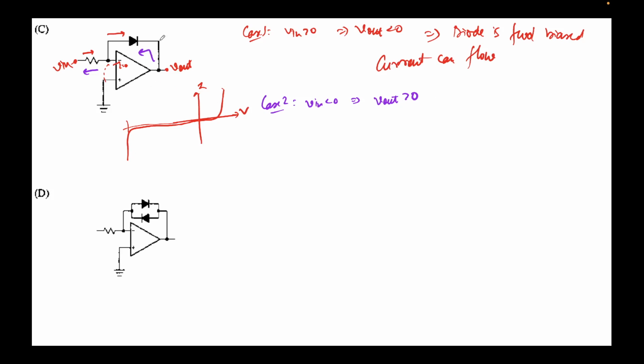This is virtual ground, while the N terminal is connected to a high, greater than 0 voltage. This means the diode is now reverse biased because N is at a higher potential as compared to P. So the diode is reverse biased. Reverse bias means it is operating somewhere in this region, right? Because usually the breakdown voltages are very high. And note that this current is very low, nanoamps or something.